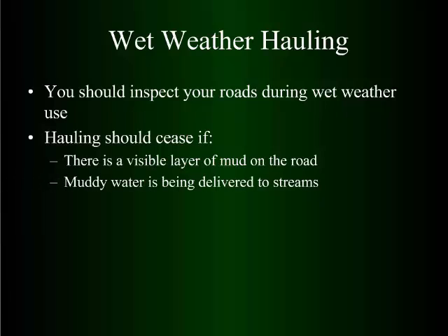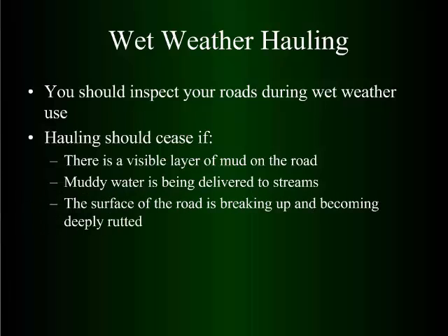And of course, the problem is you saw on the previous slide where the road was pumping and the runoff from that road ended up in the streams. And then when you saw where the trucks were hauling, the road surface was breaking up and you were getting surface deflection.